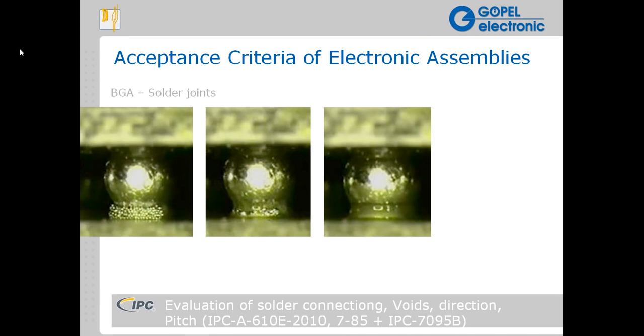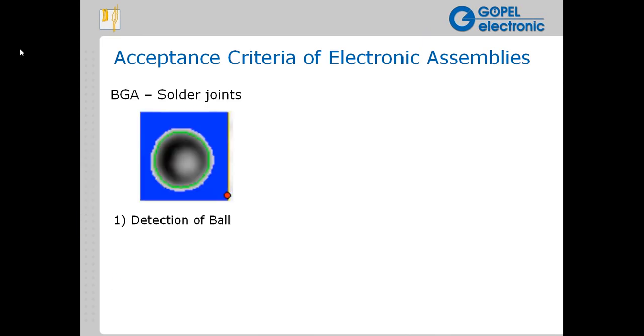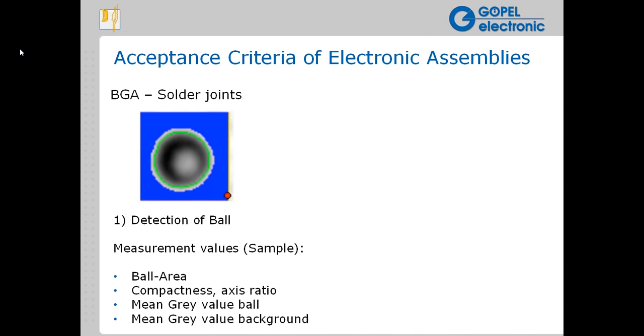Detection of voids is very clear in 3D X-ray like this. As you can see here, the density is very easily revealed. We can measure void area. We can measure the percentage of void area relative to the ball area, and as a result provide very valuable metrics in terms of being able to guarantee certain criteria relative to voiding of solder balls.